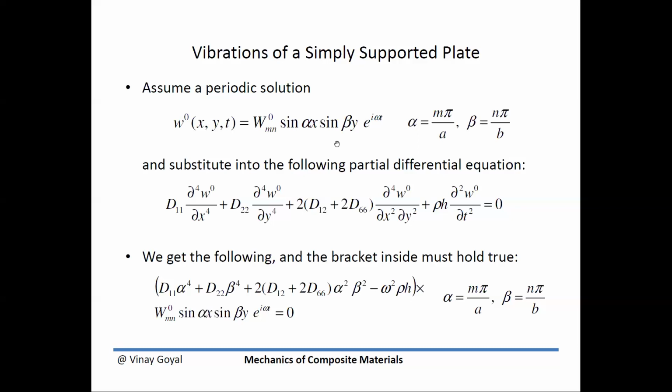The same turns out for this term. So you can see how around the edge, it does satisfy the boundary conditions if the plate were a by b. We also notice that at the edge boundaries, the moments are also zero, and that entails a second derivative of W. And again, the second derivative of a sine function gives you a sine function again. And so you can see how automatically this also supports that type of boundary condition. So this satisfies those boundary conditions exactly.